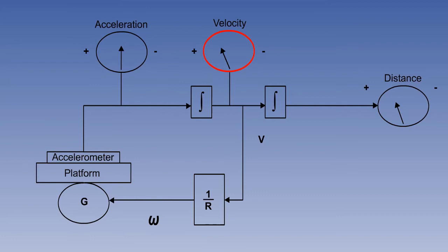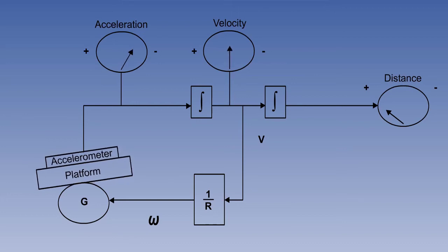The way that an integrator works is that if you have zero acceleration going in, it doesn't mean that you have zero velocity going out. It means that you have zero change of velocity. Therefore, the velocity continues to be passed to the second stage integrator and to the position display, displacing the position further. And it also continues to be passed back along the V over R loop, thereby rotating the platform as far over in the opposite sense as it was at the start.